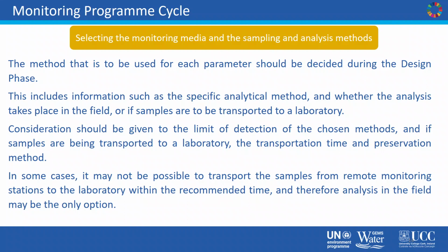In some cases, it may not be possible to transport the samples from very remote monitoring stations back to a laboratory within a recommended time frame. So each analysis has a recommended holding time, which is how long the sample can be held before analysis. Therefore, in those cases, it may be better to do an in situ analysis using one of the field methods available.